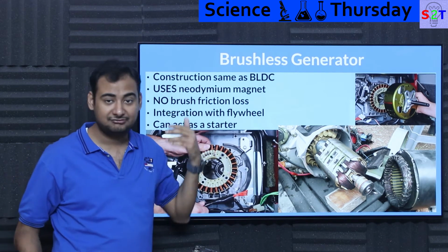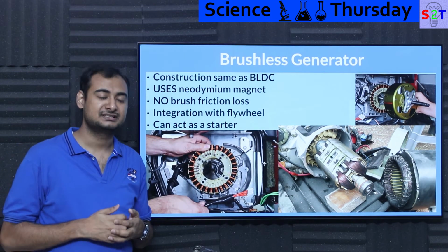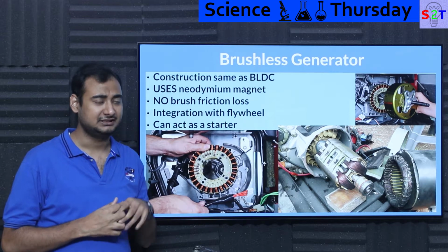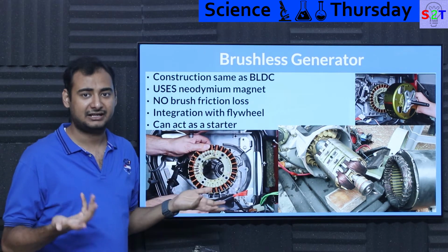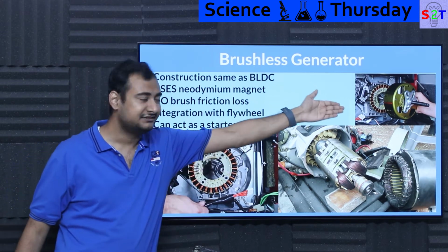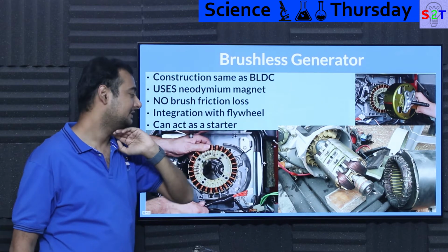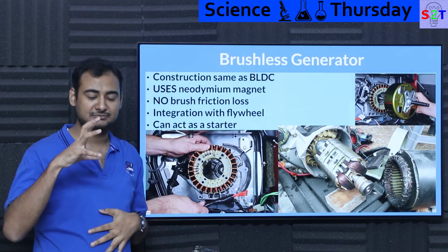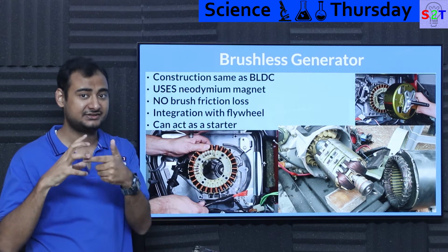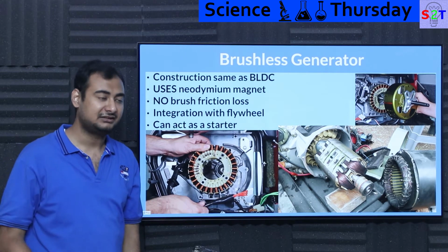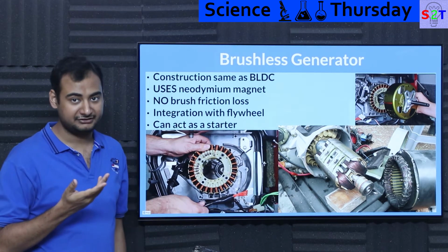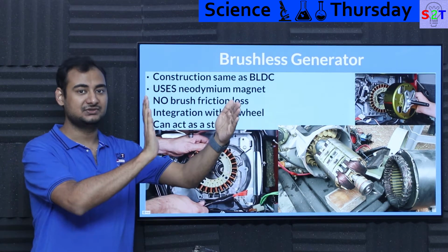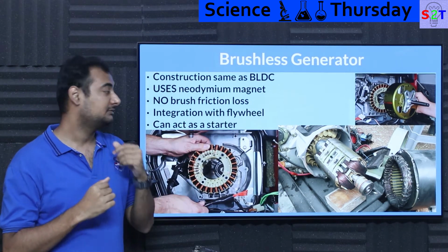Well, because every combustion engine, especially with one single piston, generally needs a huge flywheel. So they thought, why the heck just have a flywheel, which is dead mass, when the rotor of the generator unit can do that? So that rotor has a giant metal mass. On top of that, it has huge magnets. So it has enough inertia to act as a flywheel. So they're like, let's get a combo benefit out of it. Your generator went from this big to this big. It became smaller, easier, more portable.